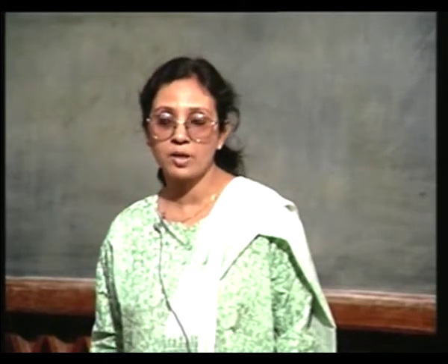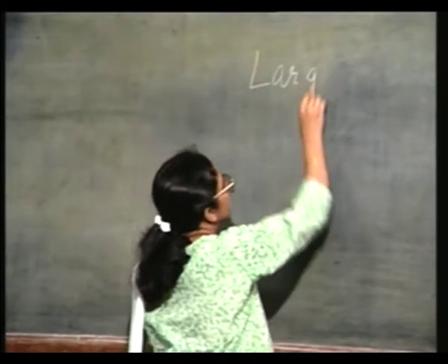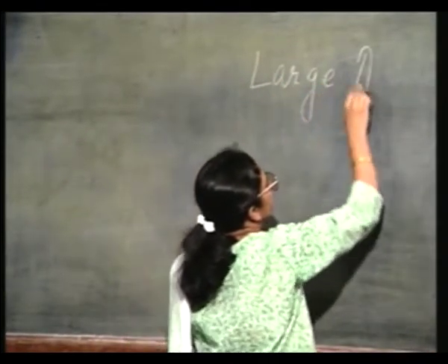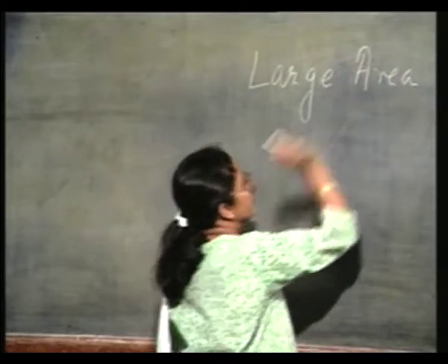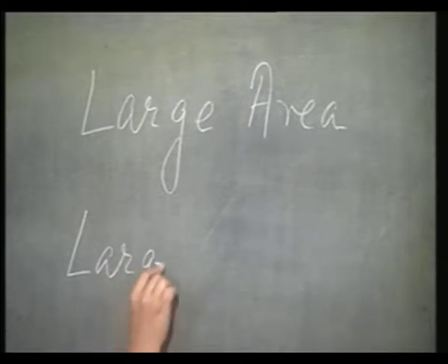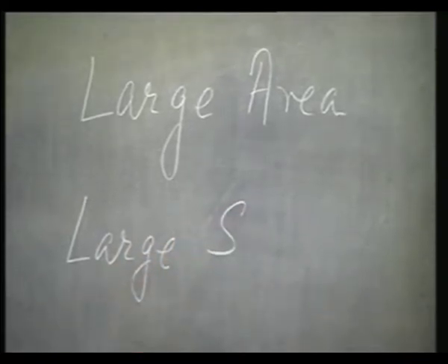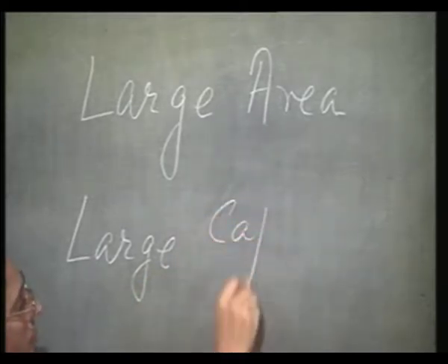The first drawback is the large area requirement, and secondly it has the adverse effect on the speed by having a large capacitance.